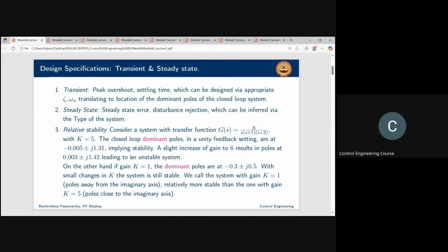Okay. So the first thing that you need to notice in design specifications is that the design specifications will all be, at least in time domain. So root locus design is also called time domain design because you're designing in time domain, right? Whereas Bode plot design or Nyquist plot design are called design in frequency domain because you'll be drawing frequency plots, okay, sinusoidal response. This terminology is first clear.